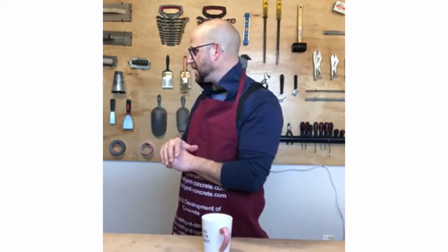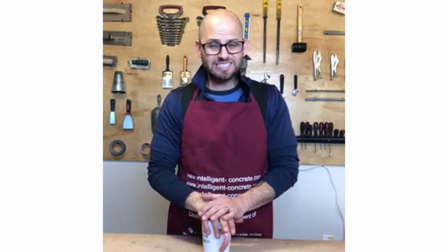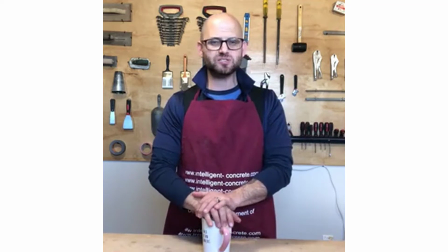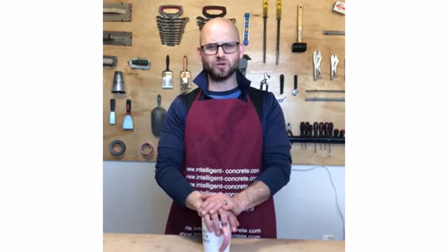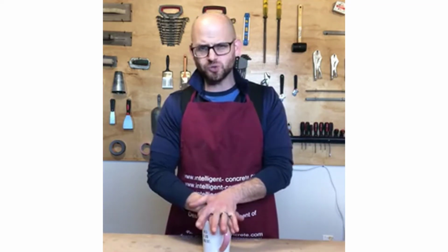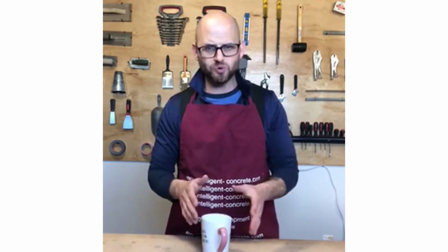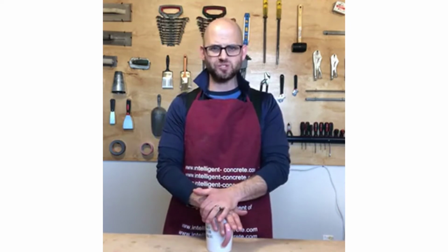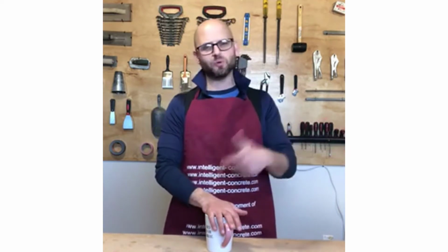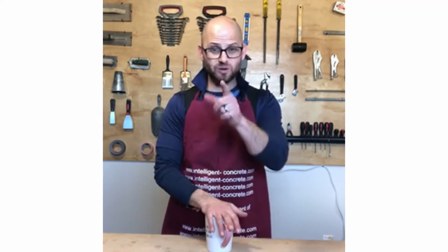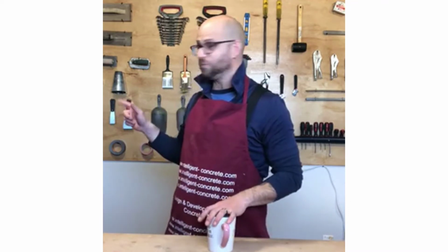So the mix design that we're doing today is for an interior slab, 4,000 psi f'c. So really want to shoot for somewhere around 5,200 psi for our design strength. So we looked at both a 0.47 and a 0.58 water cementitious ratio. I think in the calcs we did a 0.47 going for that higher strength. So pretty excited for that, and we're pretty excited to get into it. So stay tuned. I've got to do a little camera moving.